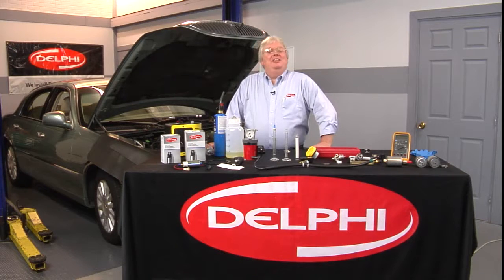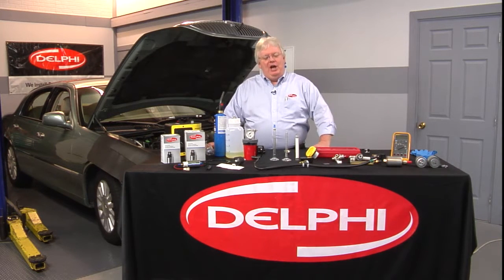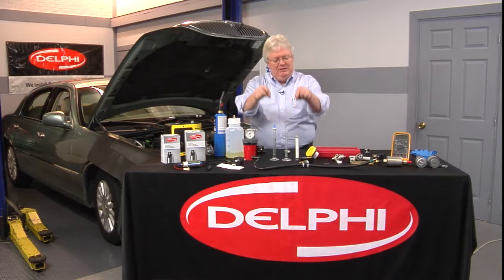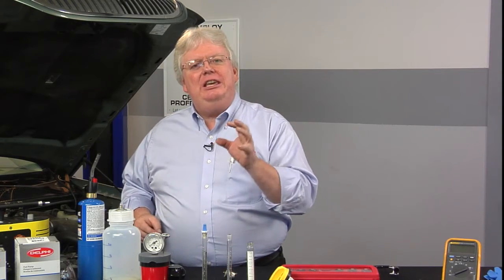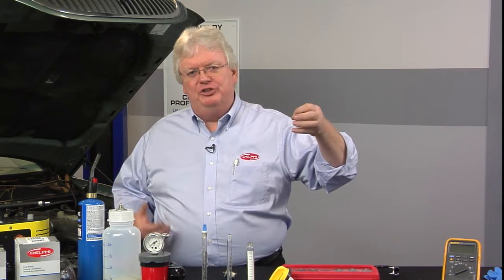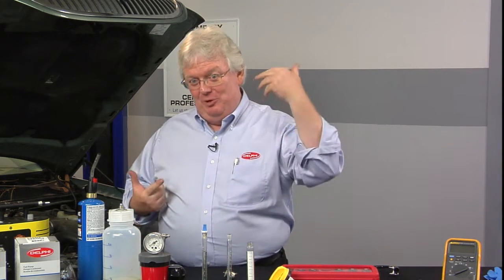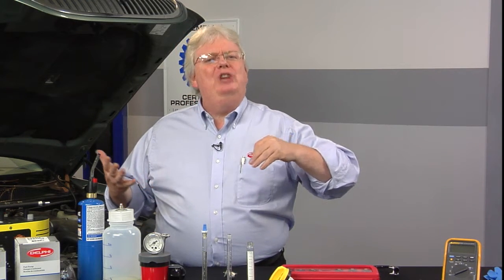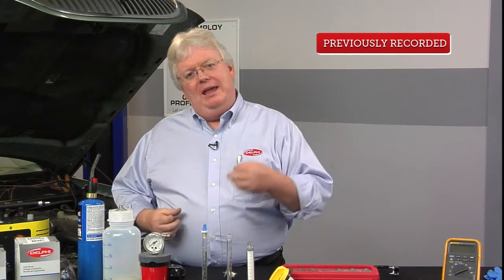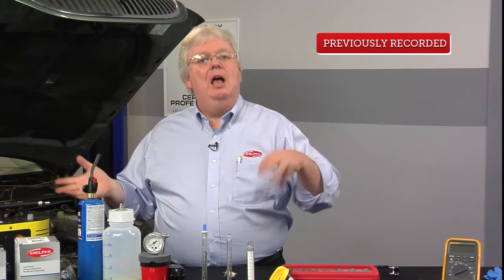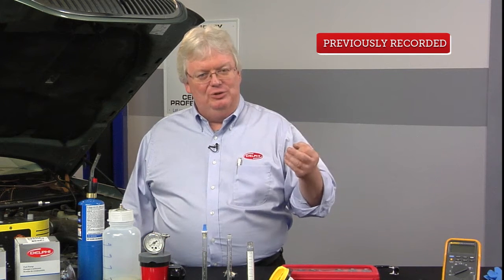Here's a question from Dawson, Dave. What effect do gasoline additives have on fuel trim? Dawson, they have a lot of effect on fuel trim. I want you to think about the little hands-on demo we did with the alcohol content. If you look at the ingredients of, let's say, fuel line antifreeze, if you live up north, then that's a problem. Fuel injector cleaner, the main component is isopropyl alcohol. Alcohol, whether it be methanol, ethanol, it's alcohol. And it's going to dilute out the gasoline to a lesser power, lesser BTUs, and that's going to make a leaner mixture, and that's going to make the trims go higher.